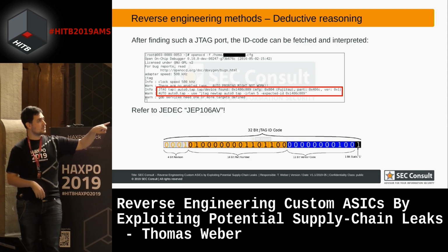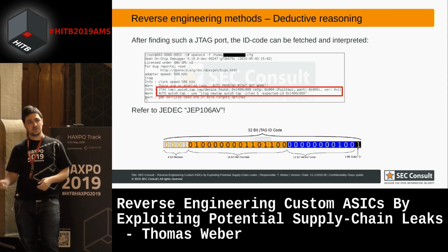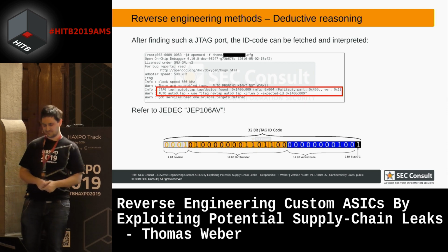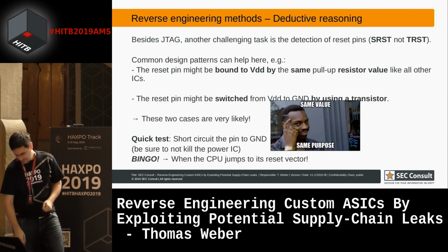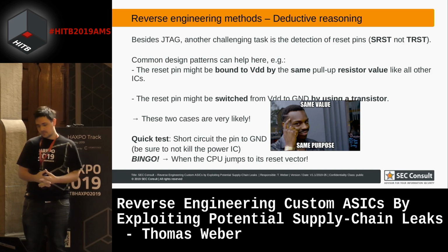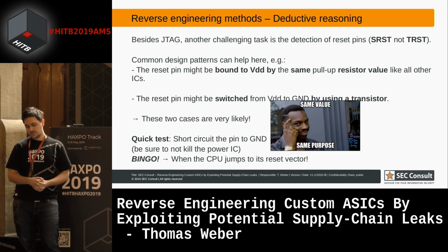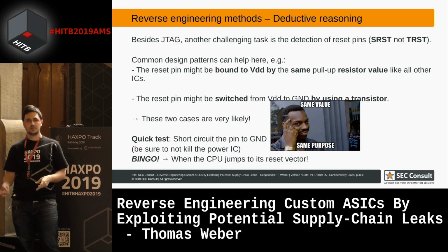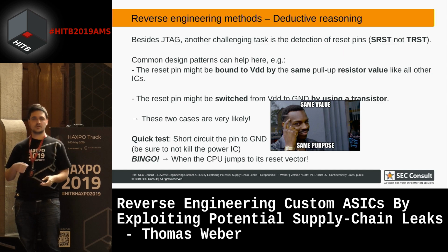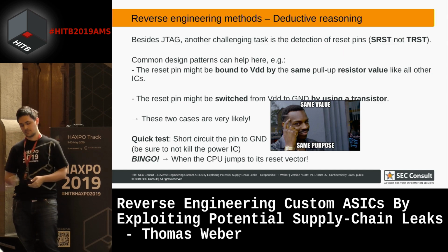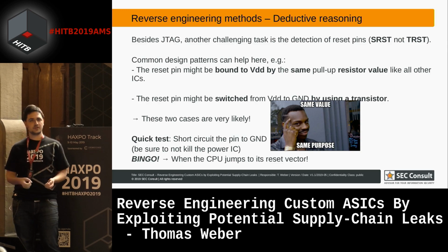And the last bit is always 1. So when you get a chip ID which has a 0 as last bit, then it's maybe not right. So yeah, there are also some other interesting things, because when you brute force the JTAG interface, you do not get the reset, the system reset, just the reset of the state machine of JTAG. And yeah, I was thinking about how can I figure that out.